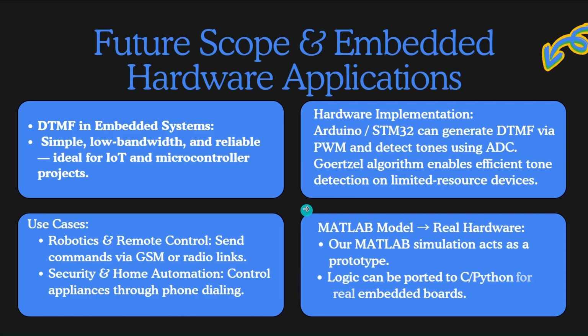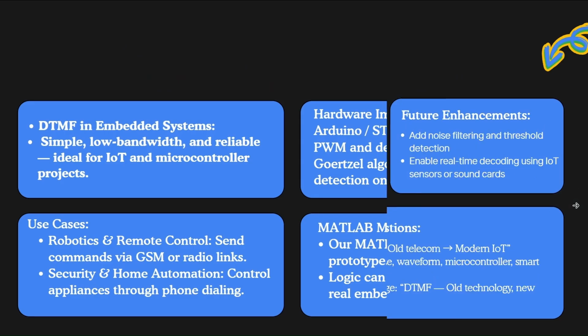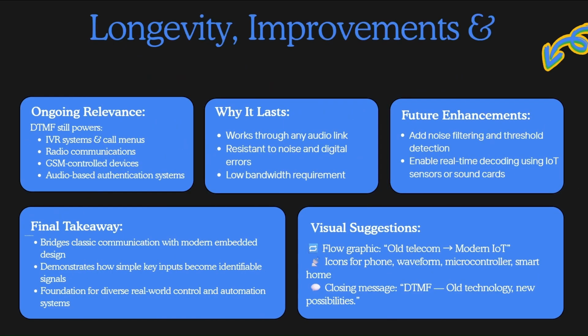Our MATLAB model acts as a prototype, a digital proof of concept. Once verified, the same logic can be ported to C or Python and implemented on embedded boards. For detection, many systems use the Goertzel algorithm, which is computationally efficient for detecting specific tones, perfect for microcontrollers with limited resources. Now, let's talk about future longevity.